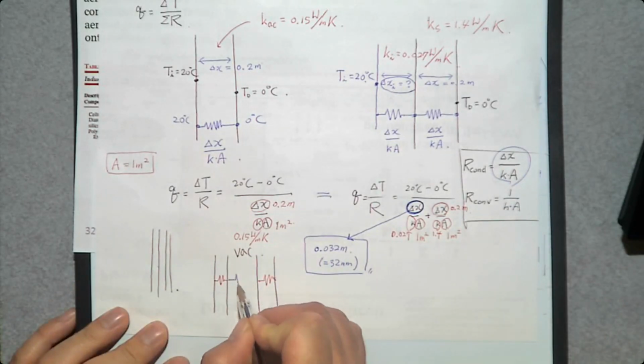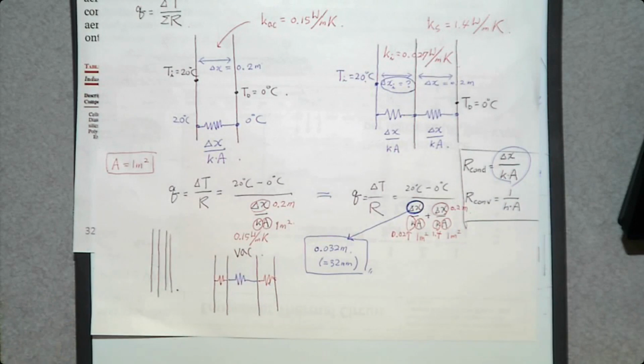Then the next question is going to be, is this glass as hot as the sun? Not really. Then how much radiation do we expect? Extremely small. That's how you design this thermal. We have a vacuum cell between these two layers. So it has two layers and there's a vacuum between.